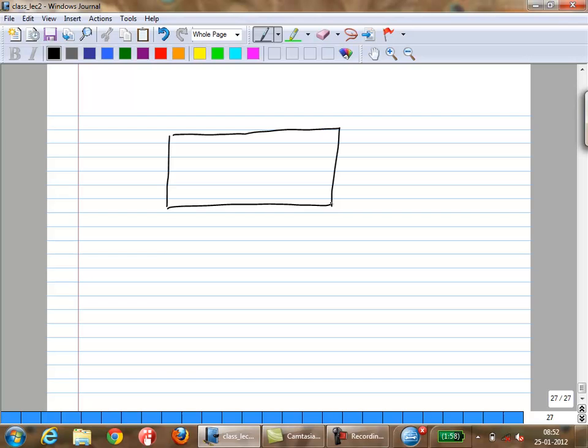So let us say we're going to lay these out with 2 fingers. We have looked at this layout before, right? Basic layout we have looked at for the transistor. So let us say this is M1. You've laid out 2 fingers for M1. Okay. How many fingers do you need for M2? 4 fingers, right? It's 2 twice.